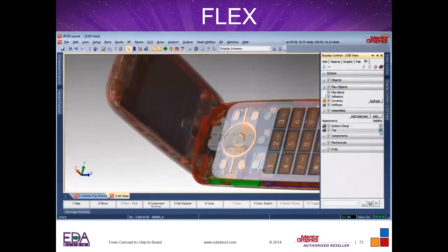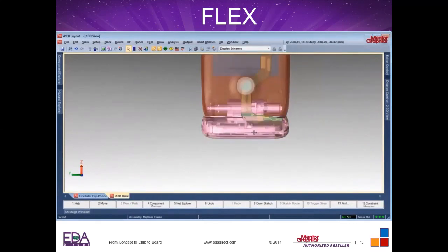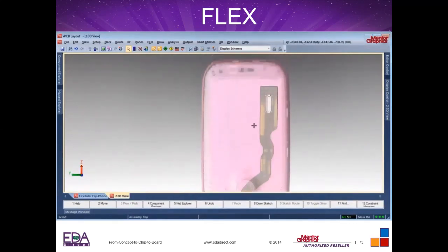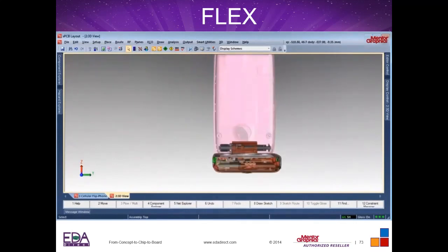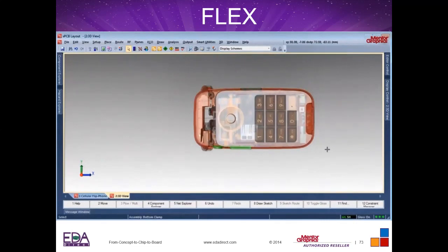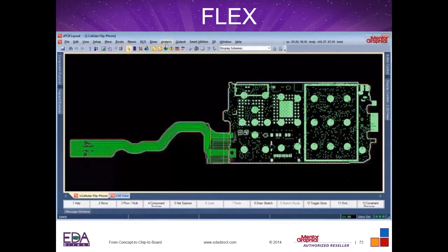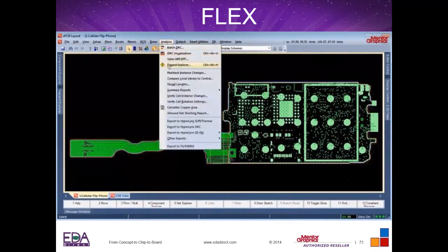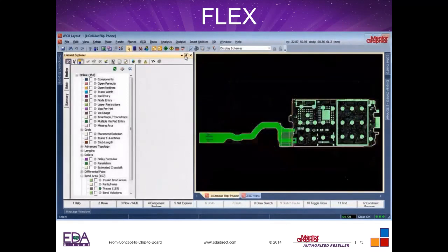Collaborating on bend areas, multiple outlines, multiple stack-ups, bend properties, and more ensures that all requirements in the ECAD and MCAD domains are met. Flex designs have critical design requirements that must be met in order to ensure quality of the overall design. Before the data is sent off to be fabricated, Expedition provides robust, updated design rule checks to identify critical issues. The Hazard Explorer helps identify problems immediately, so issues can be corrected long before the design is sent out to be manufactured.